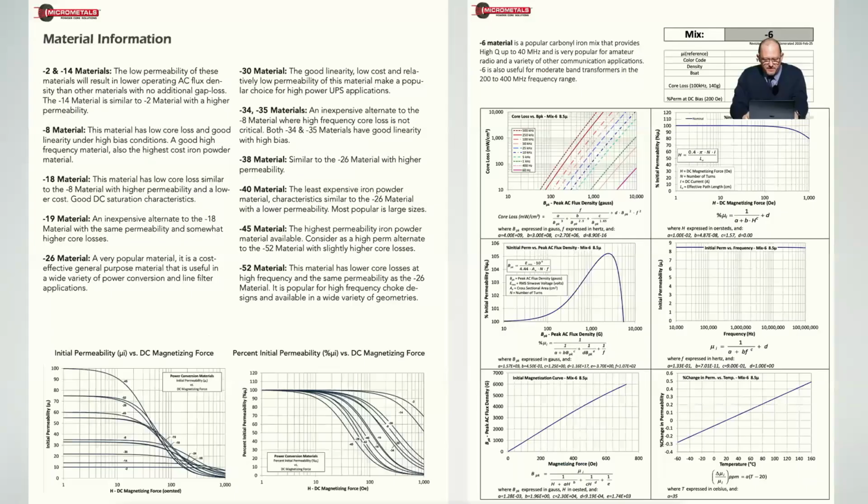And then this is for powdered iron, which interestingly enough, there's not really that many types of powdered iron that's used by amateur radio. Generally, it's going to be type 2, type 6, and type 8. There's only a few of interest. And then maybe a type 0, which doesn't actually have any permeability. It's essentially what you'd use if you just wanted to use air as your core.